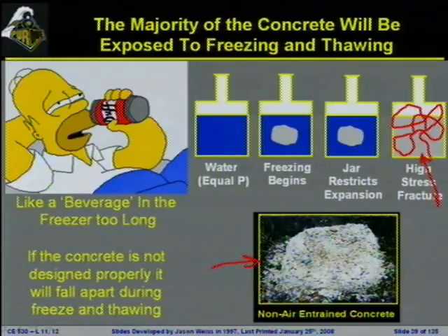All right, this concrete was left exposed. It was non-air entrained concrete. When the water inside of the system begins to freeze, it creates a pressure that will cause a fracture inside of the system, will cause the concrete to disintegrate and start to fall apart.